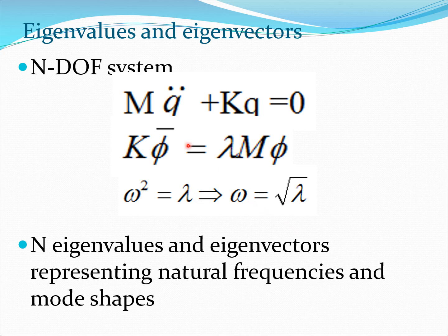Now typically you have an n degree of freedom system, so this problem will essentially be solvable, and the eigenvectors of this particular problem, that is the phi here, represent the mode shapes. So that's something which also comes out to you by simply solving this mathematical problem. So essentially the physical problem has become a mathematical problem, and it can be very easily solved in computers.